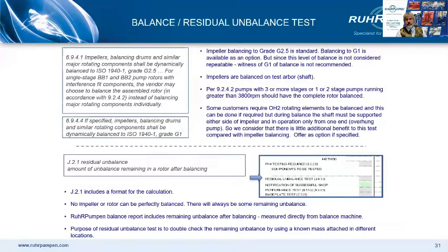But not only are the results unrepeatable, which means if you balance the part, take it off the arbor, put it back on again and check, it will give a different reading. So not only is it unrepeatable, but per the reference standard, ISO 21940, it's inappropriate.